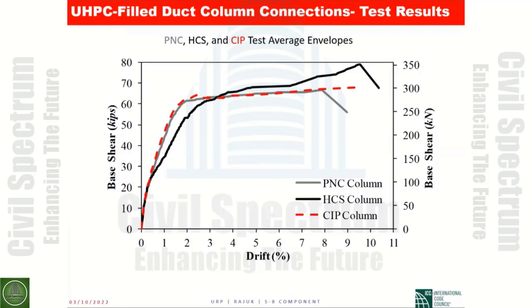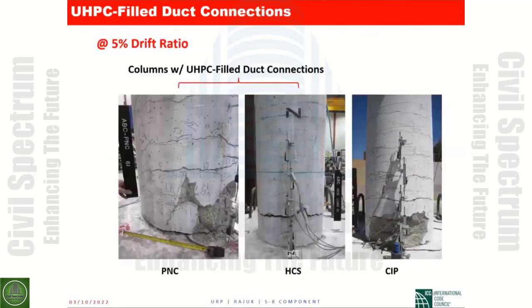The one that used the shape memory alloy, again, comparable, but we ended up with a lower stiffness. This is because of the lower stiffness of the material that was used, the reinforcing material. The shape memory alloy was made out of nickel titanium that has lower stiffness than steel. Also, the strain hardening characteristics of the material is a little different. That's why you see the dark black curve has a larger strain hardening characteristic.